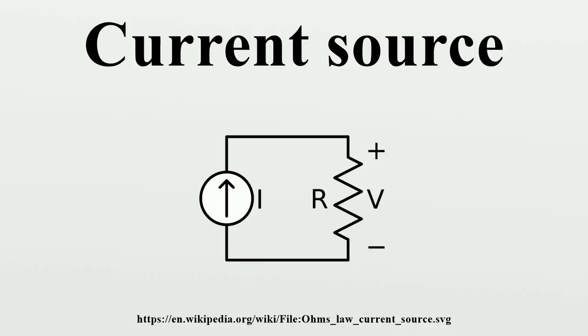Imagine in Figure 5, at power-up, that the LED has 1 V across it driving the base of the transistor. At room temperature there is about 0.6 V drop across the VBE junction and hence 0.4 V across the emitter resistor, giving an approximate collector current of 0.4 mA.